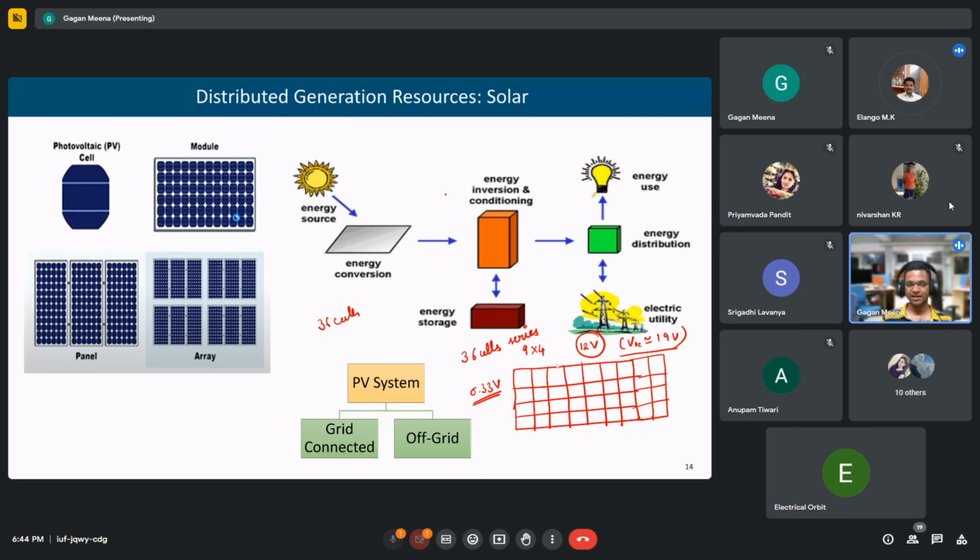It depends upon the material we are using: monocrystalline, polycrystalline, thin film. Which material produces 0.33 volt, sir, for this configuration? That I will have to check. I don't remember. Okay, sir. Thank you. But VOC is certainly different. We will see in a subsequent slide when we look at the characteristics. VOC is when no current is being drawn from the panel; then the voltage across its terminals will be VOC. But at that time, it cannot produce any power because no current is being drawn.